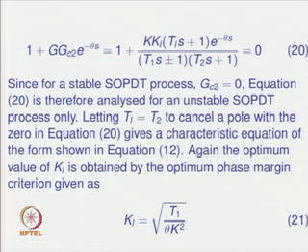With the choice of TL equal to T2, one term in the numerator and denominator will get cancelled. So, cancel TL s plus 1 and T2 s plus 1, with the choice of course TL equal to T2. Then it will render a characteristic equation of the form 1 plus K KL e to the power minus theta s upon (T1 s minus 1).